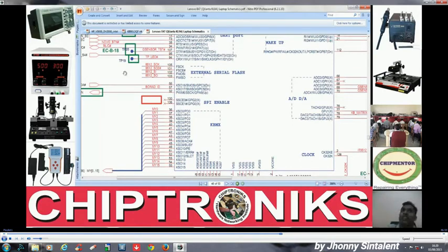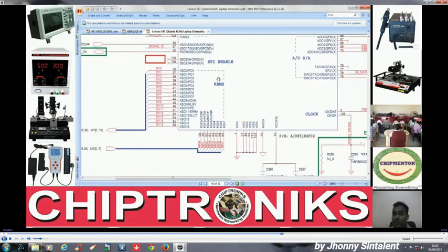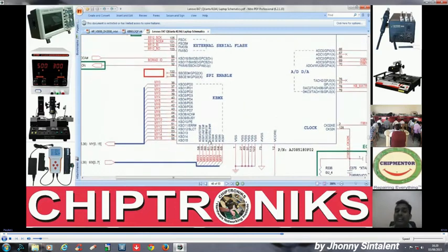We can program that flash while keeping it on the notebook motherboard, and this is a very innovative concept, that is flash direct access. We can directly access that flash via this IO controller, using the pins KSI4, KSI5, KSI6, KSI7.